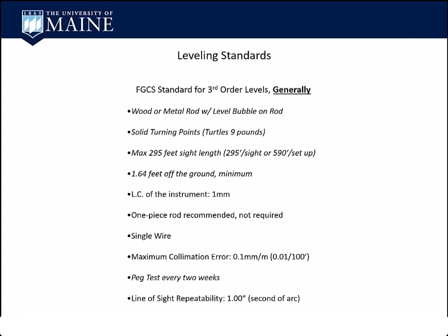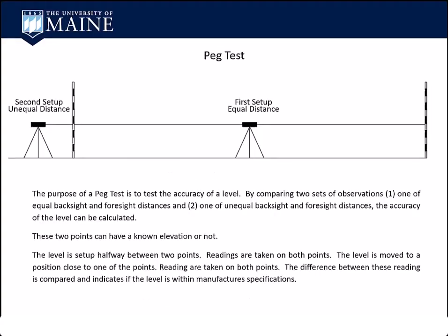It's a lot of work running levels with Invar rods, but you can do it. It's not a big deal. So we talked about the peg test and knowing if your instrument is working properly. So I'm just going to walk you through a little exercise in a peg test.